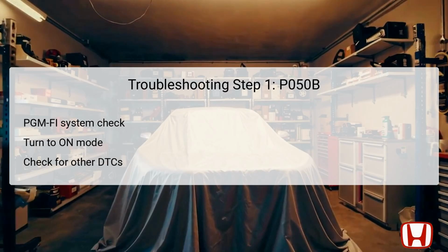It's crucial to note if there are any DTCs other than P050B presented in the diagnostic menu. If there are additional DTCs, the appropriate troubleshooting must be initiated for those codes before proceeding with the P050B diagnostics. If only P050B is confirmed without other DTCs, you can move to the next step in the troubleshooting process.